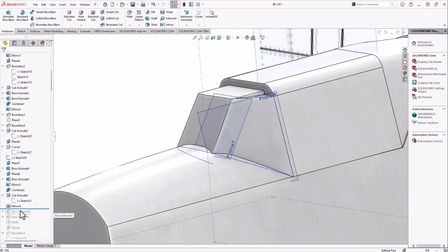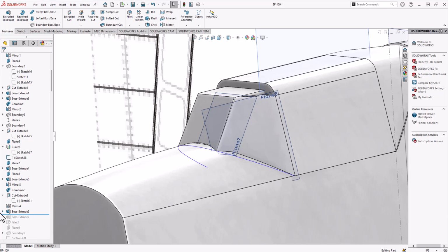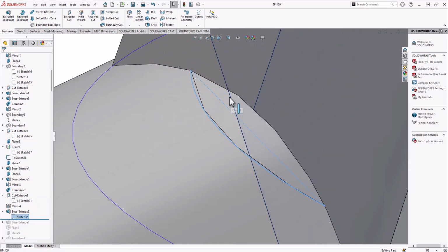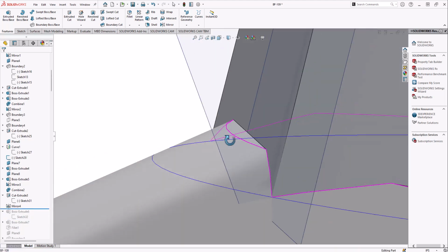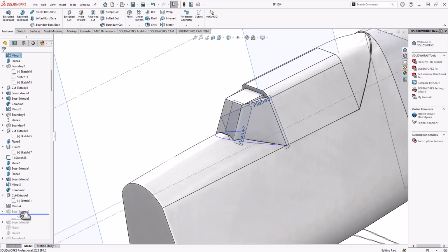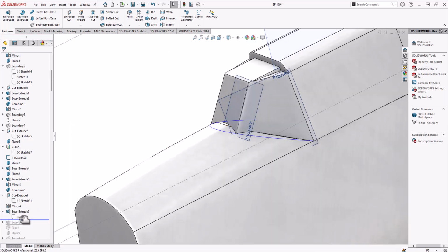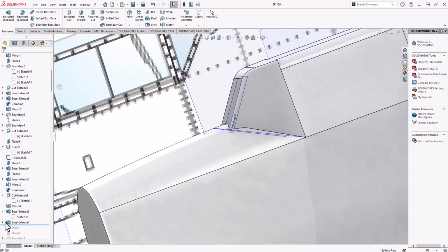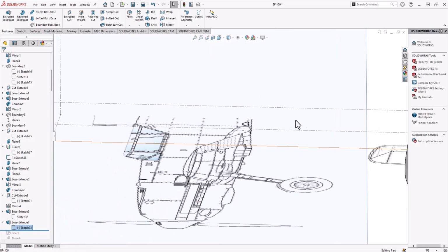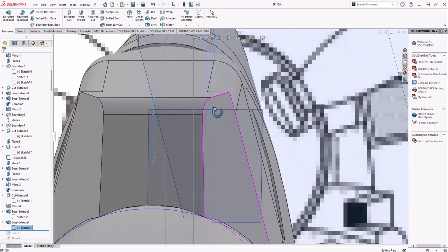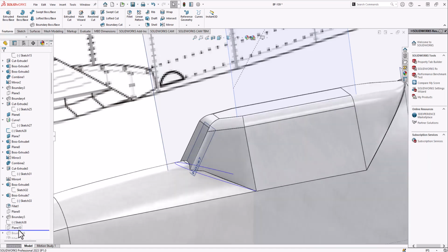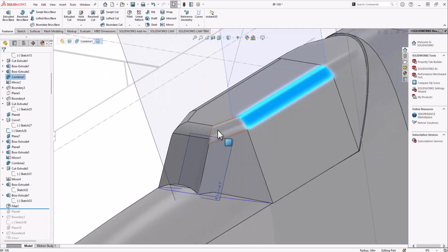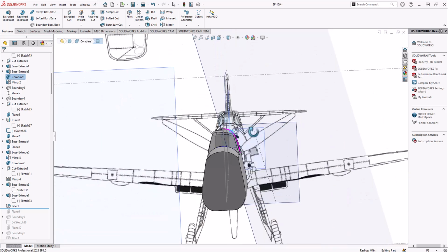That gets it on both sides, and then I just did the roof here. This is just lining up this piece right here, since it's not supposed to have a lip. So that lip I'm just correcting with that extrude. And then the next extrude is, I believe, this one. This is on the midplane, and I extruded it equally in both directions, just to get out to the edge of the cockpit, and then I do a fillet with the same radius as this curve here, and it closes that off really nicely and gets the contours of the cockpit looking good.